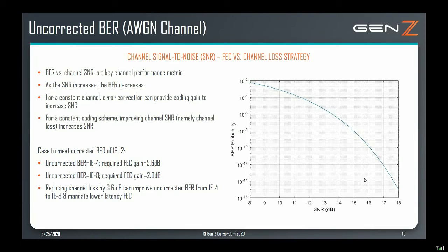So, following that train of thought, the next question is: in order to implement Gen-Z FEC in an Ethernet switch, you'd need a custom Gen-Z switch, correct? Yes, that is correct. And it's not just the physical layer that's different. It's a totally different protocol layer as well. So you can't just send Ethernet protocol traffic over the Gen-Z switch. It has to be a Gen-Z switch.